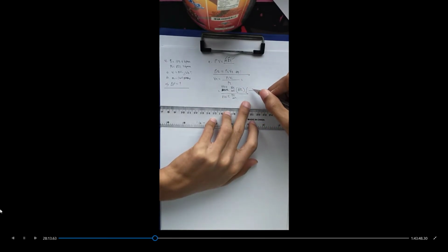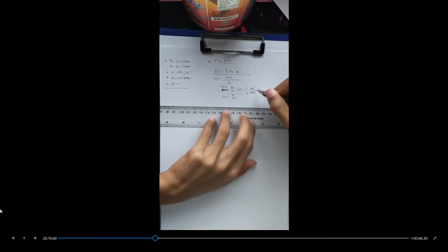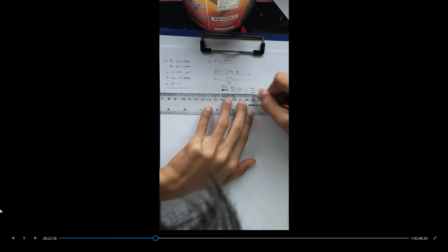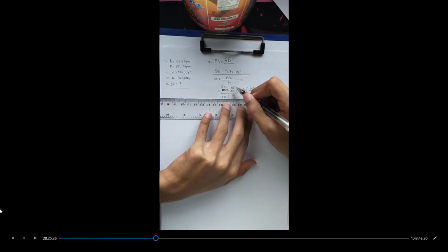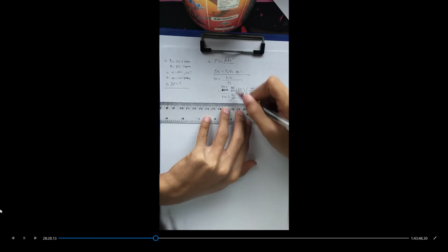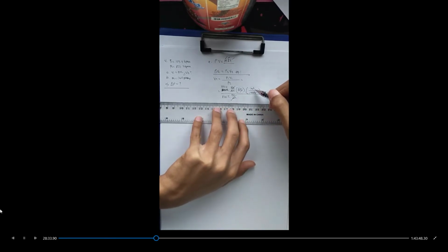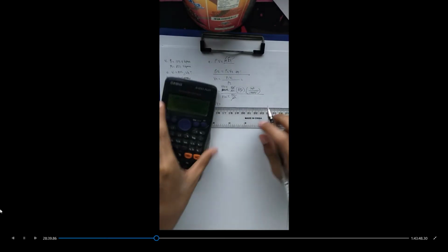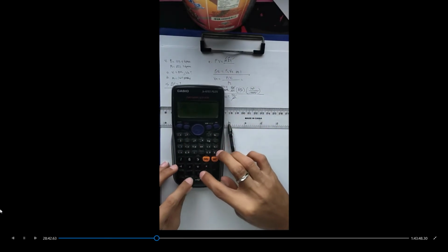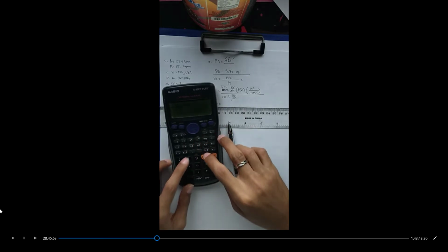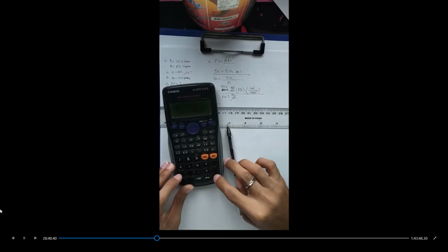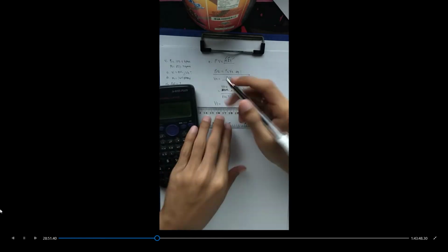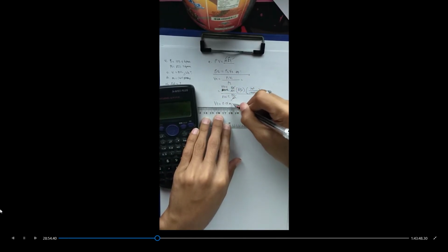So we have a uniformity of units that will be all in metric system. So 80 liters, the conversion would be 1000 liters at the bottom, and 1 meter cube at the top. So that's it, cancelling the units. Kilonewton per meter squared cancel, kilonewton per meter squared cancel, since this is in the form of division of fractions, and cancel liters. So the remaining unit will be a unit of volume in metric system, which is meter cube. So solving for volume 2, we just simply input our constants, 103.4 times 80 all over 827.2 times 1000. Our volume 2 is 0.01 meter cube.